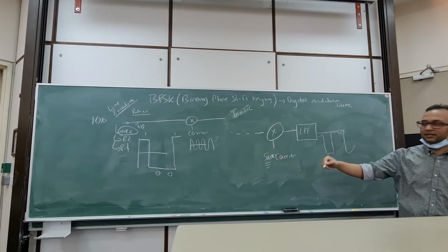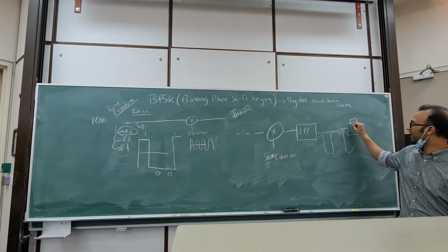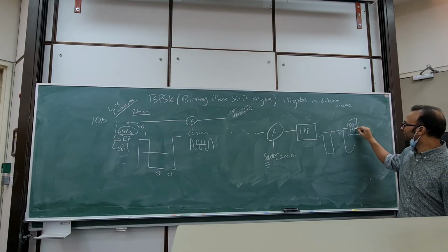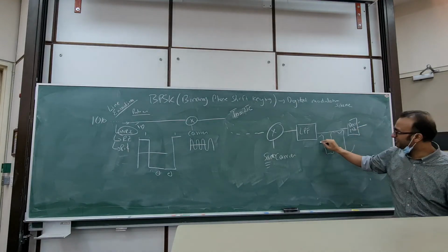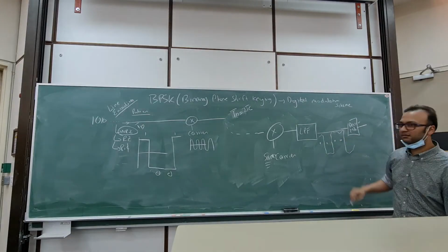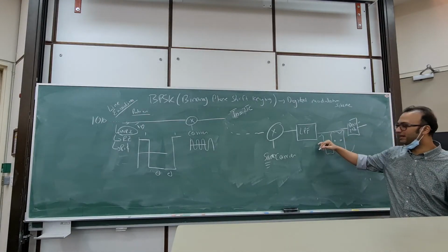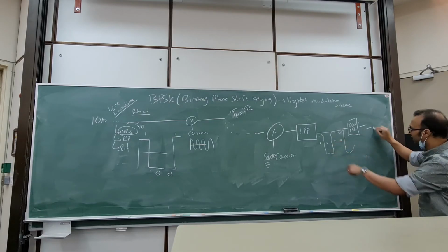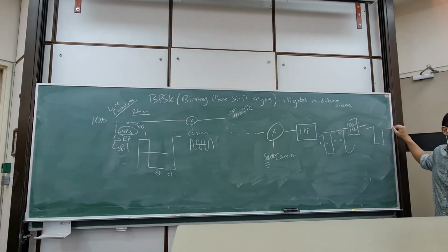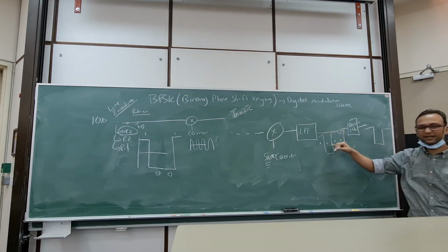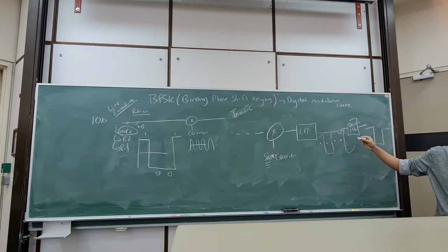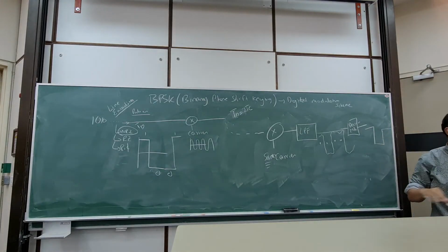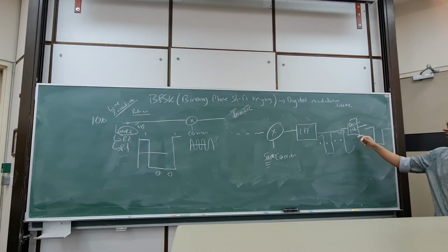What you do after this is you use another block, a decision maker. So that you take decisions at points. Whenever at this point it's high, that means it's high. If it is low, it's low. High, high. So now the signal is made proper. It's like an if condition here. If more than this, output is 1. Less, and so on. Now you got your pulses.